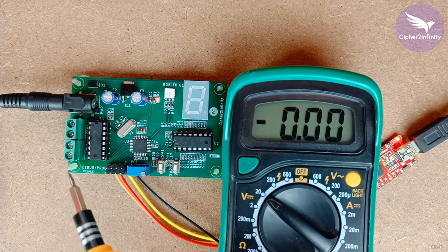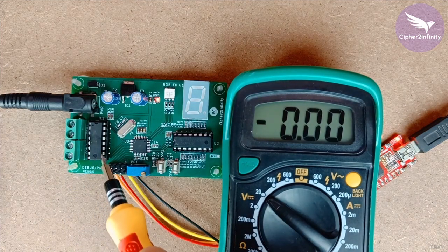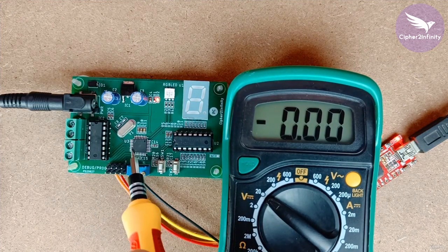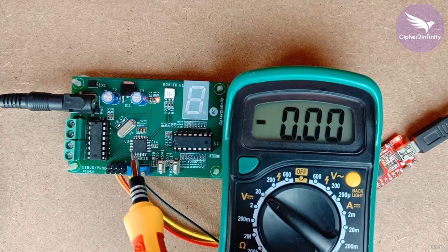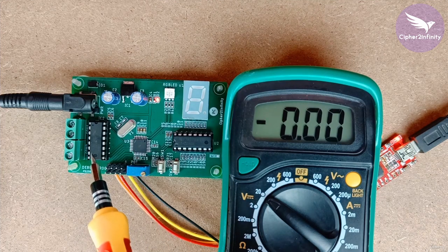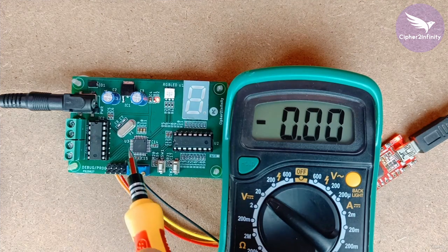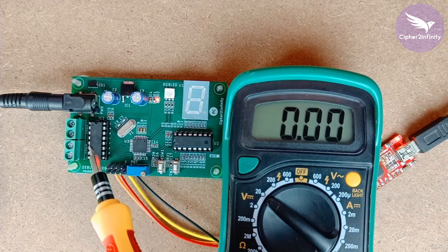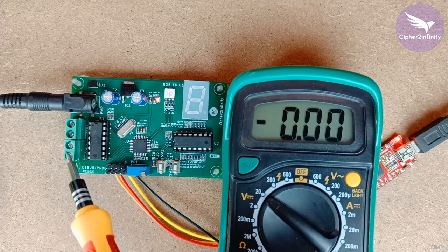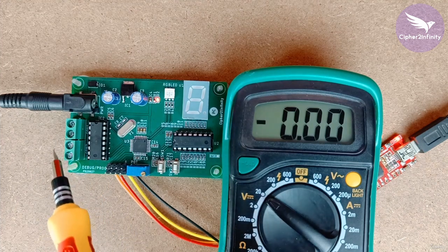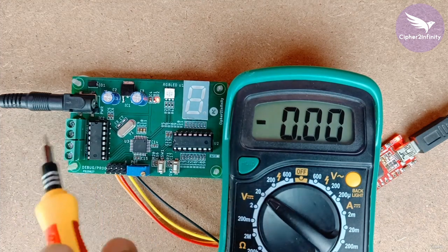So what we are doing, we are controlling the enable pin with the help of PWM pins which are present on the controller. Okay, you already know that we have connected the PWM pins of the controller to the enable pins of this L293D IC. And by using the PWM feature of this controller, we are controlling the enable pins of both the channels. Okay, and that's how we are controlling the speed of the motor.